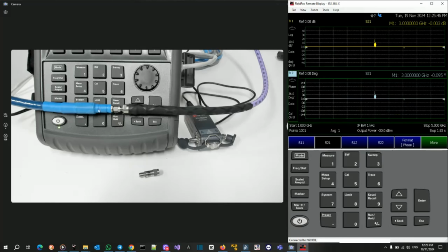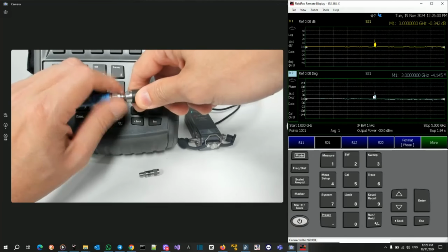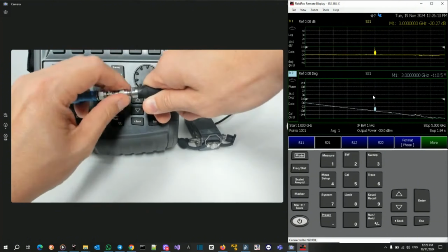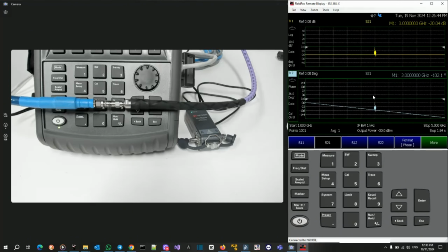As you can see, without changing anything here, we should get 0 dB. That makes sense because it's normalized, and it's also normalized in the phase measurements. Let's put back the device under test, which is the attenuator. This is the reading, and it makes sense. It's about -20 dB loss, and this is the phase property. Let's put that into memory.